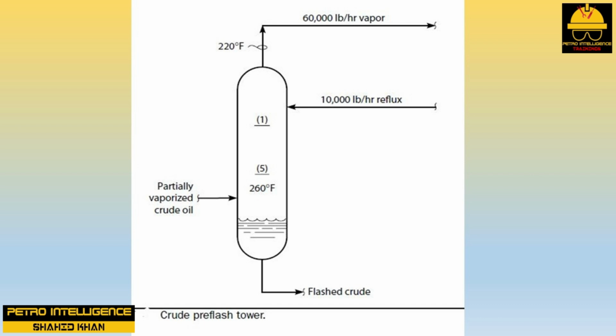The main reason why the vapors leaving the top tray are cooler is vaporization. In other words, the sensible heat content of the flowing vapors is converted to latent heat of vaporization. But what is vaporizing? The reflux, of course. The sensible heat content of the vapors, which is reduced when the reflux rate is increased, is converted to latent heat as the vapors partially vaporize the incremental reflux flow.